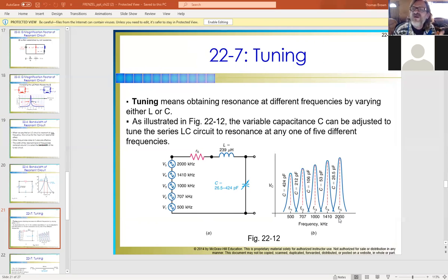If 105.2 is your station, we could still possibly hear the signal at a little different frequency, like 105.1, but you start getting noise. It doesn't sound real clear. And the same with 105.3. You possibly might still get the signal, but a lot of noise. It's not getting to where it wants to be as far as the bandwidth is concerned.